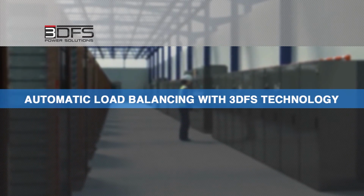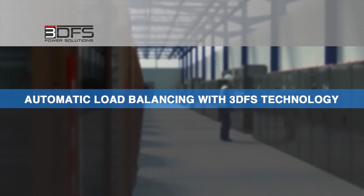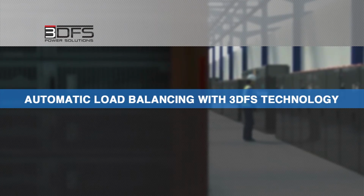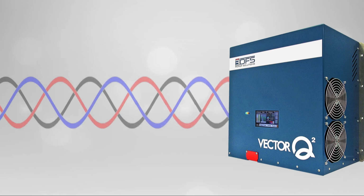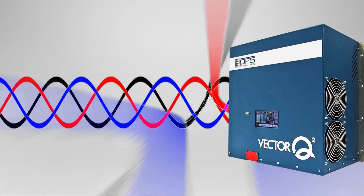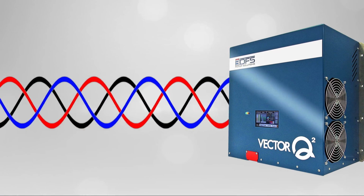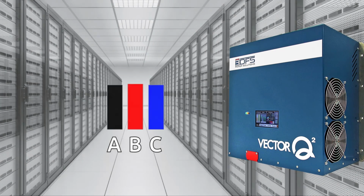Now we will show how 3DFS technology is the first commercially available product that automatically balances the loads across the phases, eliminating human error from this process. The power controller analyzes the real-time power demand and immediately optimizes electricity and reports data through our secure user interface. During this process, the load balance across the phases is also monitored and corrected, providing dynamic load balancing at all times. The automatic load balancing feature comes standard with the Vector Q2 unit.